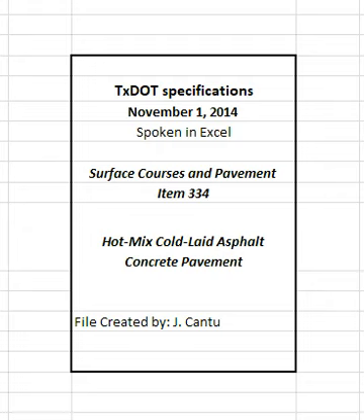The engineer may accept an existing mixture design previously used on a department project and may waive the trial batch to verify JMF1. Provide the engineer with split samples of the mixtures and blank samples used to determine the ignition oven correction factors. The engineer will determine the aggregate and asphalt correction factors from the ignition oven using Tex-236-F.